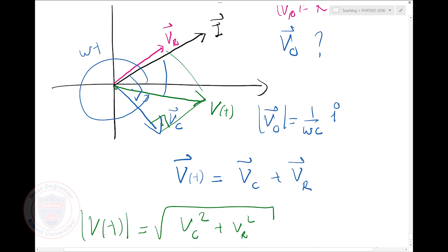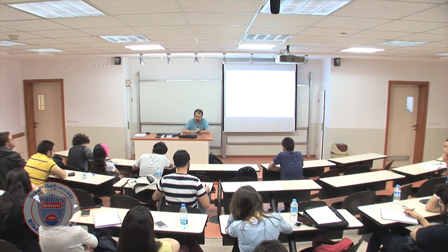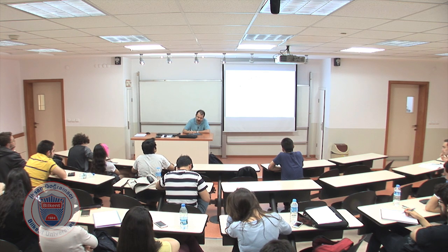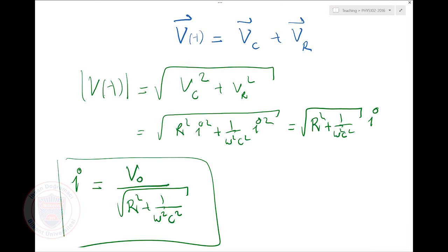So what I need to find out is the phase. My current is in front of my voltage, apparently. And what is the tangent of that angle? It's going to be VC divided by VR. What is VC? 1 over omega C times I. What's VR? R times I. So it's going to be 1 over omega C R.